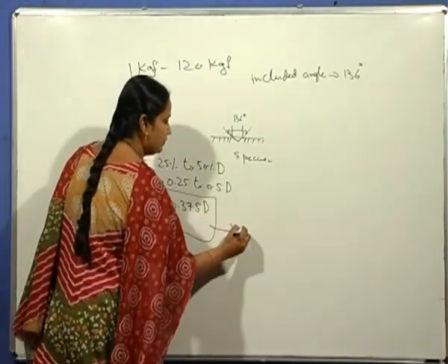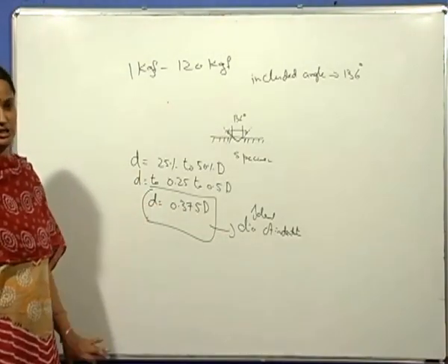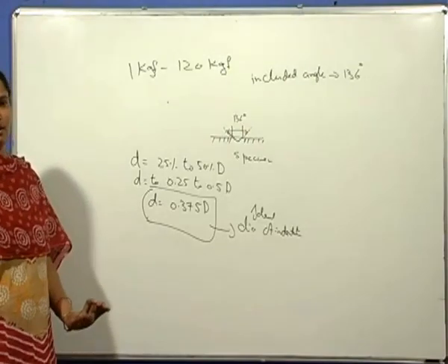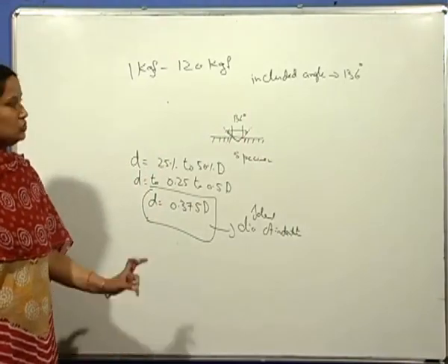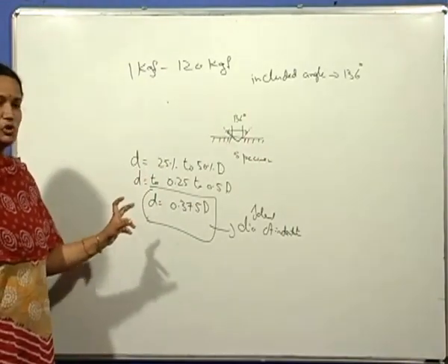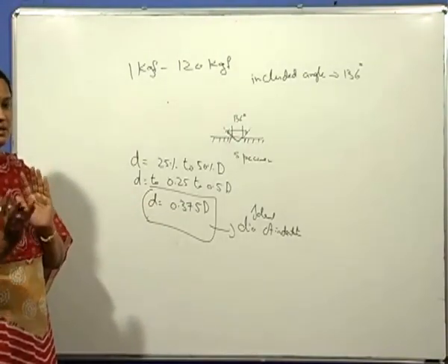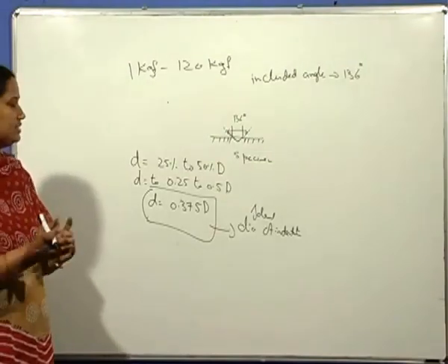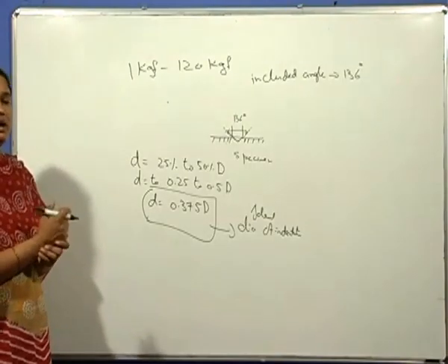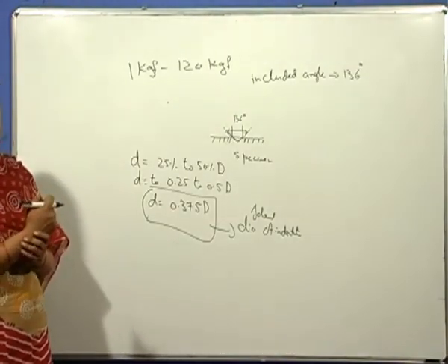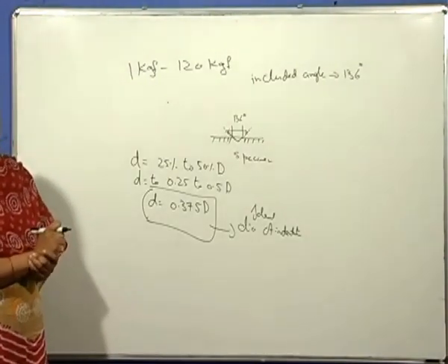So this is the ideal diameter of indentation. Based on this ideal diameter of indentation, when tangents are drawn, the angle between the tangents is 136 degrees. Smith and Sandland chose this angle so that there would be some similarity between the Vickers hardness and the Brinell hardness values, because Brinell hardness was very well established by the time they introduced this pyramid indenter.